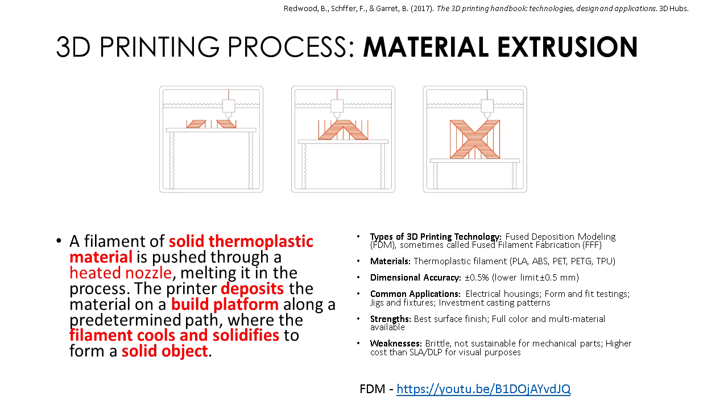For FDM, there are a lot of materials. They have PLA, ABS, TPU, PVA, even the glue itself can be melted. So if you can see here, the filaments are coming from up and go through this nozzle, as we call it, forming a pattern layer over layer to create an object. All right, so go through this: the material, the dimensions, accuracy, common applications are over here and whatnot. You can read it out.